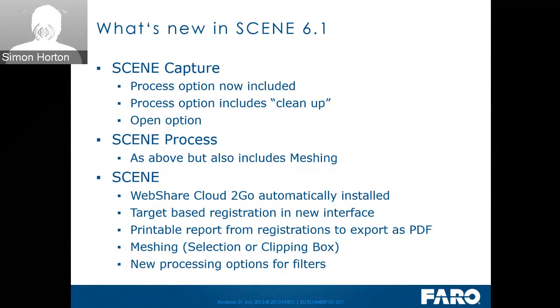We then move on to Scene Process, which, as you may know, is a cut down version of FARO Scene. In here, as well as allowing the open option and the cleanup option, we've also integrated meshing. So if all you're doing is simple scans, cleaning them up and creating meshes, you can do that in Scene Process. Moving on to Scene itself, in version 6, we created a new solution called WebShare Cloud to Go.